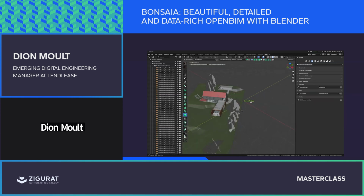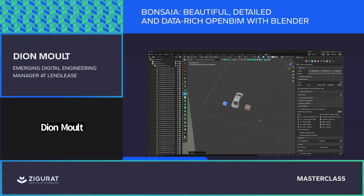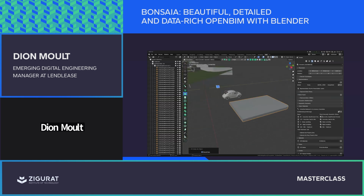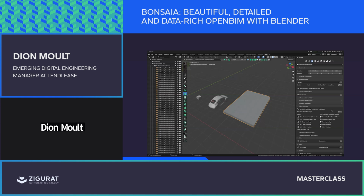Whereas if I contrast that to, let's see here, if I draw a slab, for example, you can see this floor, concrete. We'll add a floor somewhere here. This is a profiled floor. So in this case, we're using a profiled extrusion with a certain number of layers that make the buildup of this floor. So if I inspect the geometry type, I can see that's extrusion. So as you can see, it goes into quite a lot of detail about what truly is inside your models.